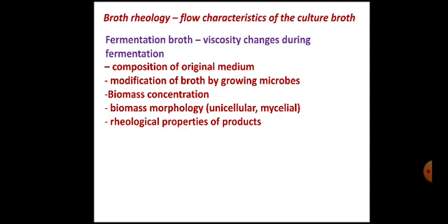Then the rheological properties of the product: microorganisms may produce extracellular metabolites or products that may be responsible for increasing the viscosity of broth. So all these are the parameters which affect the broth rheology.